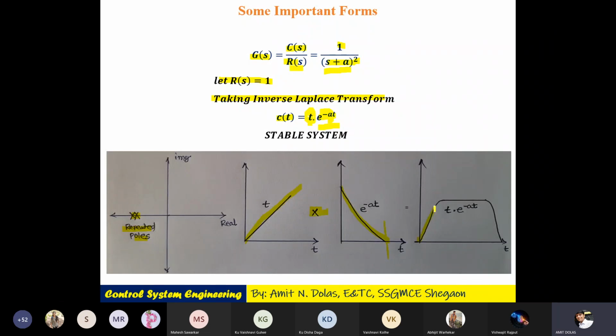It will increase, remain at a certain constant, and somewhere a peak can also be shown, and again dies out towards 0. So you can see the final output. Look at the final output, your output is bounded. And if you go for the area, you can of course find out the area of this graph. The area is absolutely integrable and the output is bounded. Thereby the system is stable. Here marginally stable is not said.